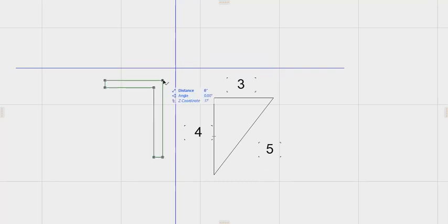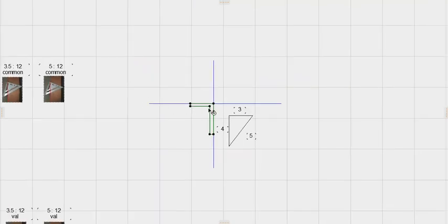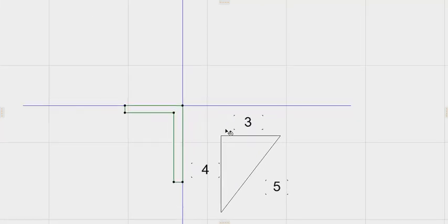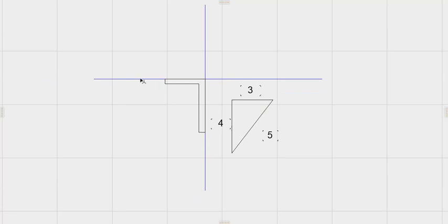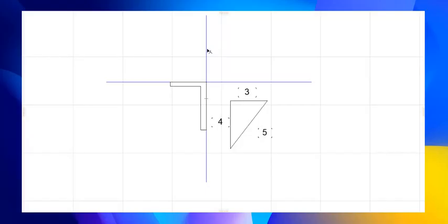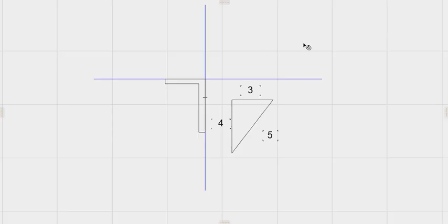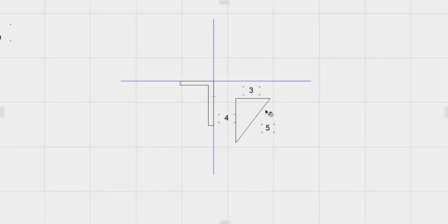If you've got a framing square, you can use it to snap through some nice perpendicular lines like that. You can check yourself by making a 3, 4, 5 triangle. If you go 3 feet and 4 feet and you pull your tape across the hypotenuse here and it doesn't add up to 5 feet, then something's wrong. And that'll be a nice grid for you to, anywhere along here you can just butt your tape there and pull off in a direction parallel to that line.